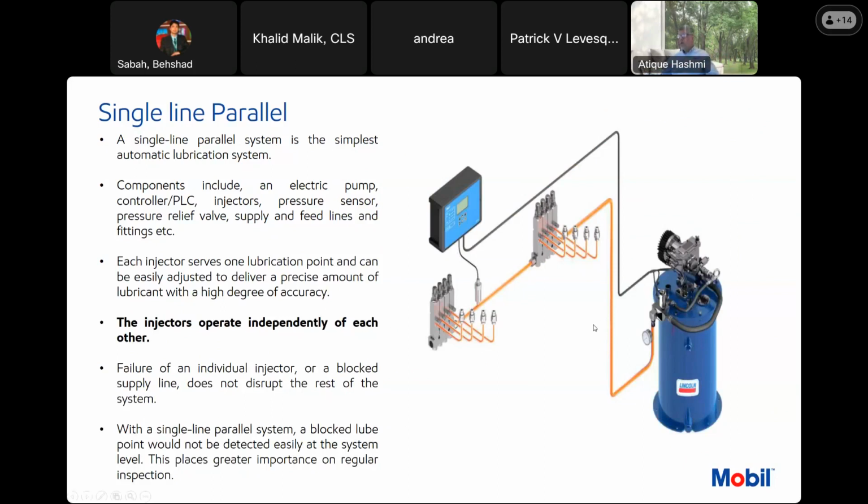Let's suppose you are running this system to the farthest point, 50 feet of machine, like it's a big machine, and you need a pressure of, let's say, 5,000 psi, and you calculated that the pressure drop through the lines and everything would be 4,500 something. At least for the farthest point, you need some pressure so the farthest lube points can be lubricated.